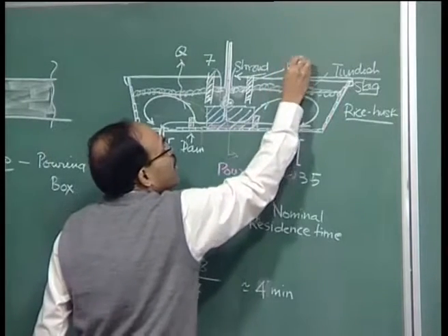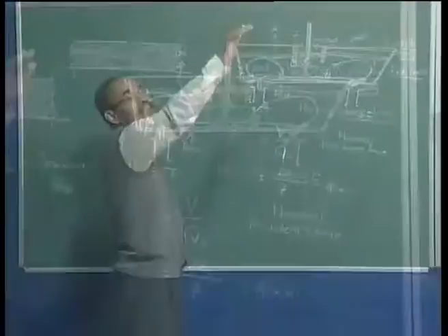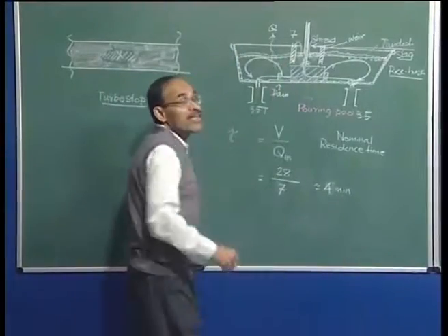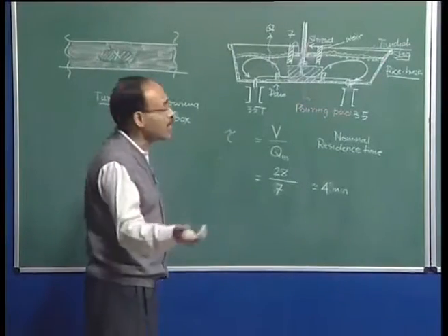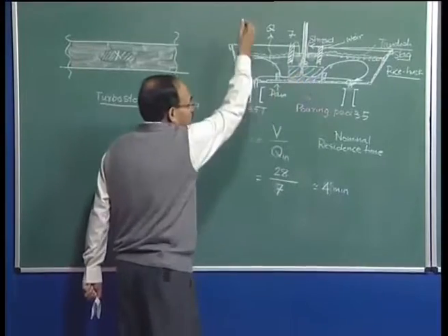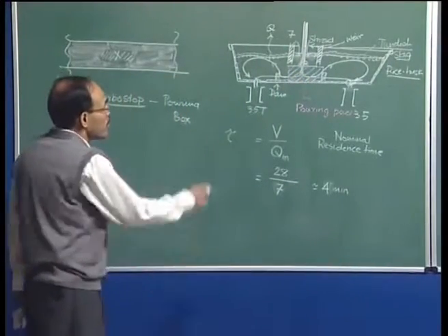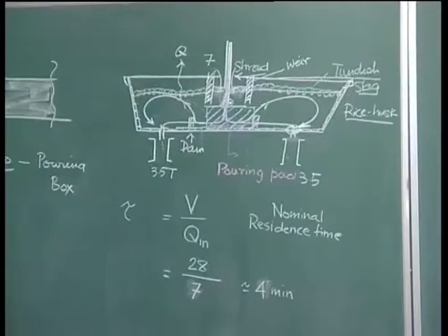So dam and weir are typically applied in combination. The objective of the dam is to produce a surface-directed flow. The objective of the weir is to not allow any slag material to move along with the melt, and that is why the dam and the weir are applied in conjunction.